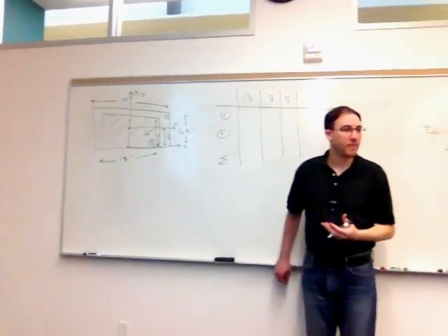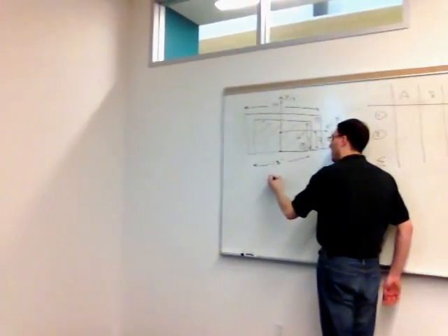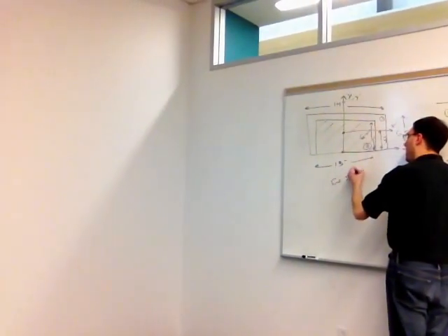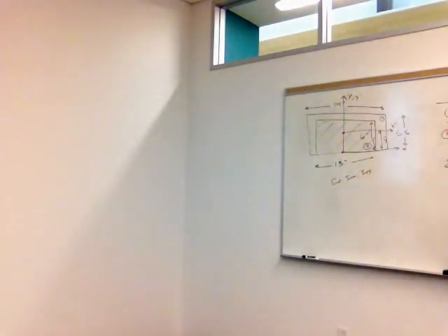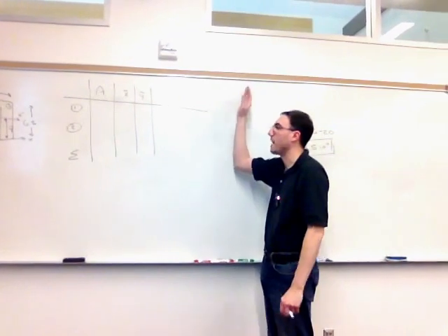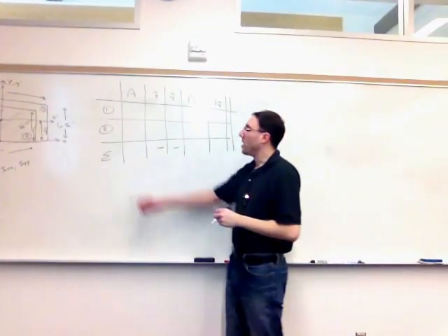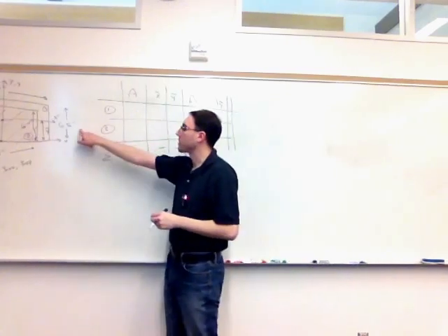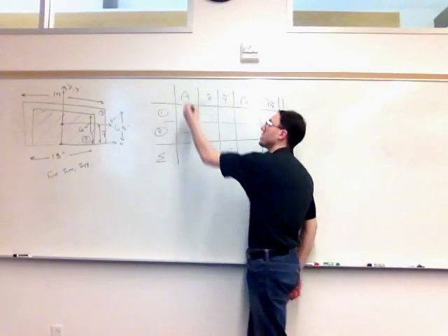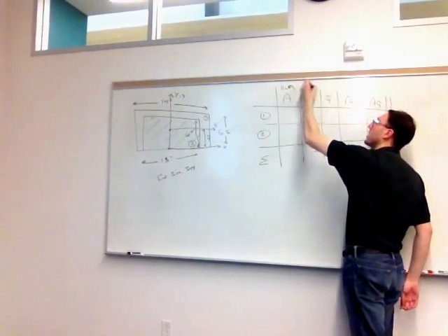In this problem, I'm asked to find both Ixx and Iyy. Therefore, I'm going to need to know the x tildes and the y tildes, because in the subsequent steps, I'm going to need the dx's and the dy's. Shape 1, the outer rectangle, is 6.5 inches by 14 inches. These are all going to be in inches for this problem. So inches.